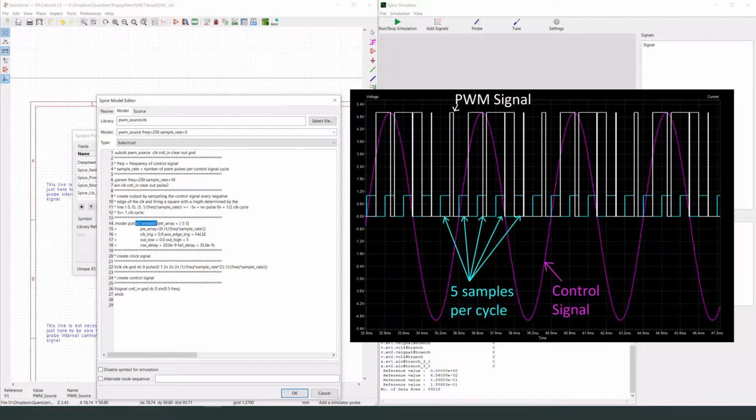And that's going to be driven by this one shot right here, which will take that sampled voltage and create a pulse that is proportional to that width. And we set that right here by this array, saying, if you're at negative 5 volts, then give me a 0 width length, and if you're at 5 volts, then give me a 1 over this equation, which is pretty much a full cycle's pulse width. And anything in between is a linear selection between those two.